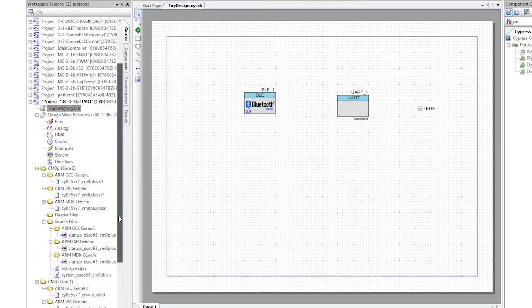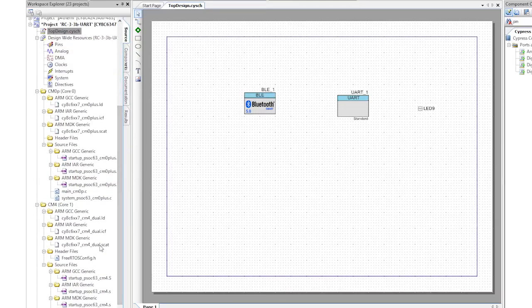All right, now let's carve up the firmware into a more manageable structure. I'll follow the template that I've been following in the main controller, meaning I'll have the BLE stuff isolated into the bletask.h and the bletask.c. And I'll have a UART-based controller in uarttask.h and uarttask.c. So start by making a file called bletask.h.